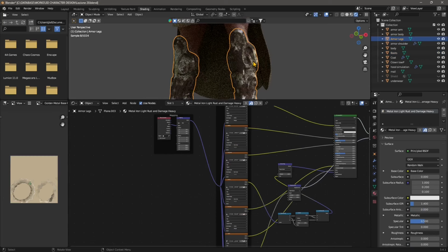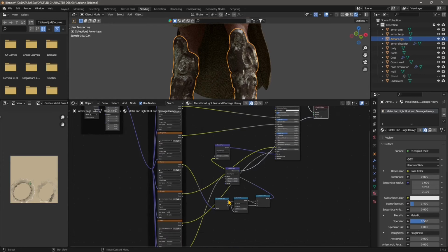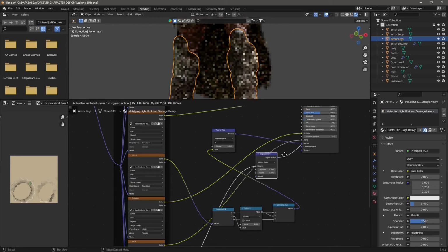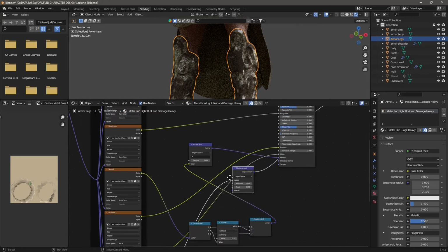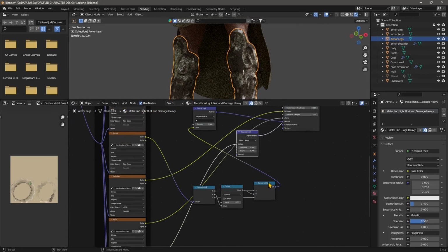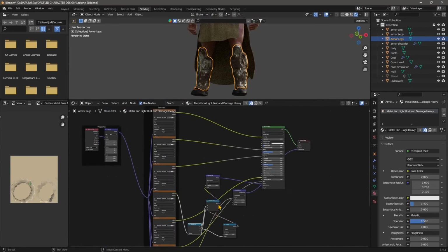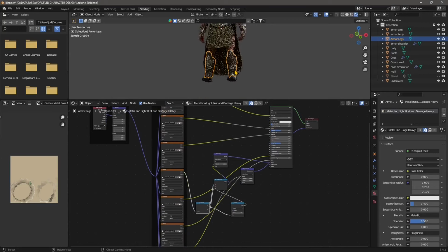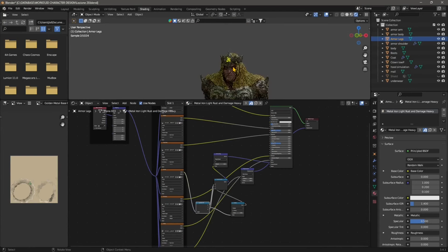So another add-on, I want to give you a couple of tips for the add-ons. Now you can see here how this was material from Blender Kit, which is an add-on, so you can use it. And if you want to map it, you can of course change the mapping. So right now we are not using the UV texture. Actually, we're using a simple tiling texture, so that we are not really addressing each single part of the object, but the material is being placed all over the object using the tiling.